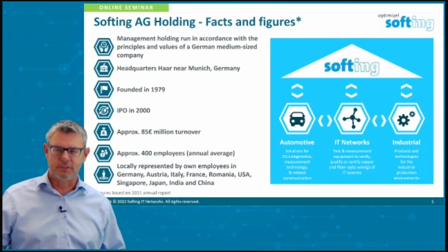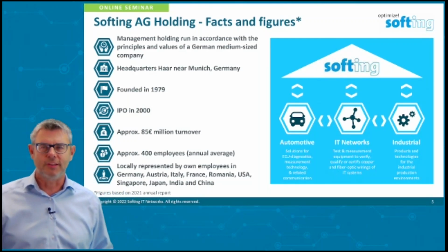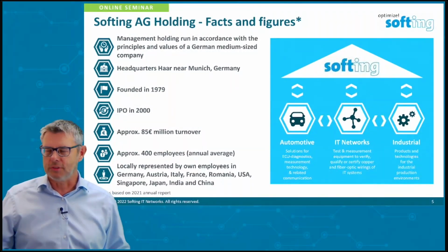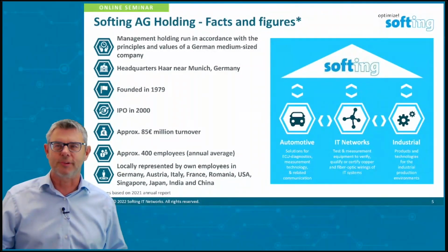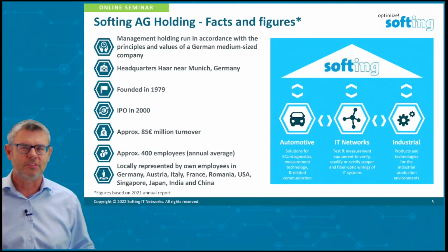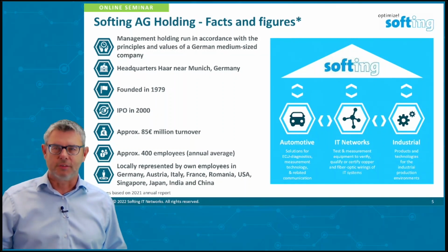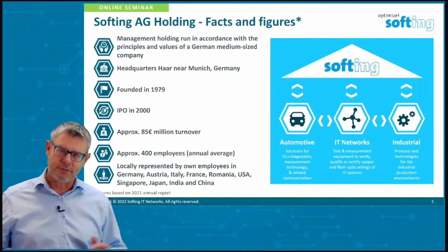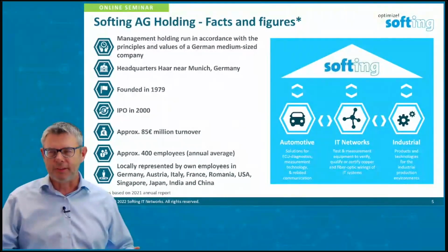In automotive, we know a car is controlled by a CAN bus. CAN bus is a very slow control bus, so it's actually too slow to be used for autonomous driving, for example. So a modern car that offers you all these nice support tools for a kind of autonomous driving is controlled by another bus system, an Ethernet bus. 10 gigabit Ethernet is very popular now in a car, for example. And every place where Ethernet is moving in, it needs separate testing of the cabling. The Ethernet protocol relies on a working transmission line.